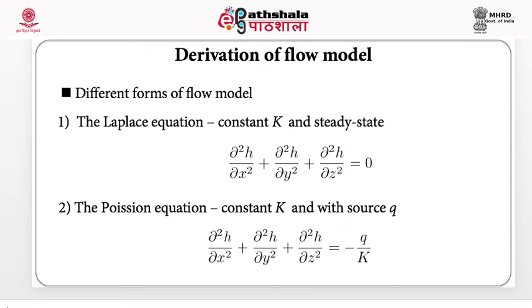Okay, when we deal with steady state problems, boundary conditions have to be defined, and in groundwater flow problems there are 3 types of boundary conditions. The first boundary condition, also called the first kind, is the one in which heads are specified at different x, y and z. The second boundary condition, or the second kind, is one in which head gradient is specified, that is dh by dx or dh by dy is specified.